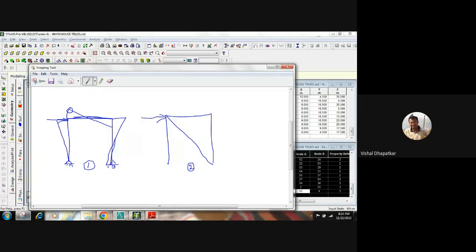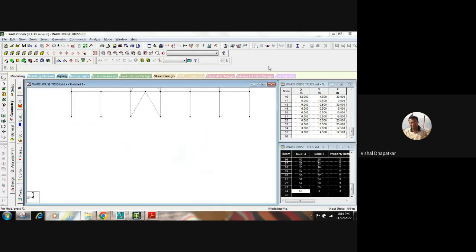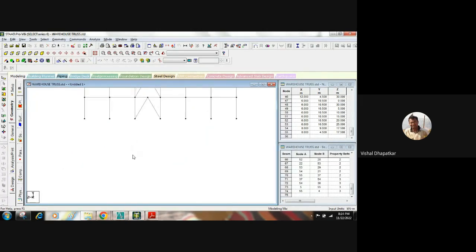Now when we provide bracing, what will happen? When we provide a bracing, that horizontal load will pass through this member as axial force, and through this bracing as axial force, right? So it will be components like this. This component will be taken care of by this beam. This component will be taken by this column. In that case, there will be no end moment, and we can simply release this member at both ends. There will be no moment. So let's check with one simple example.